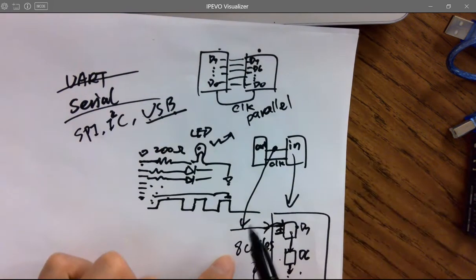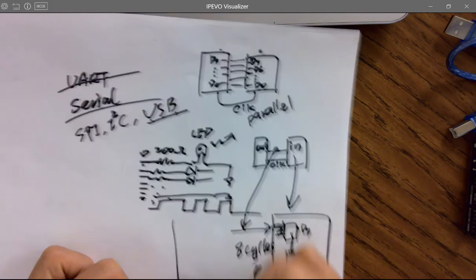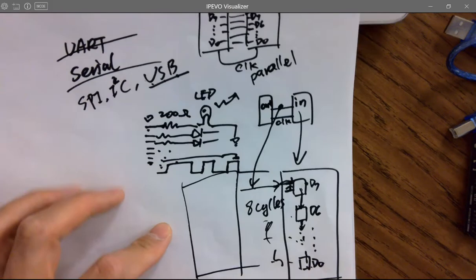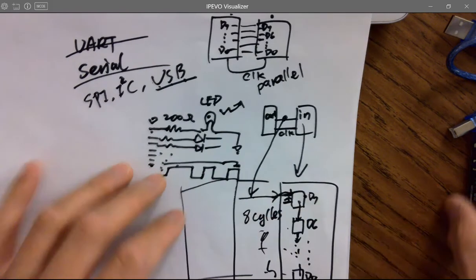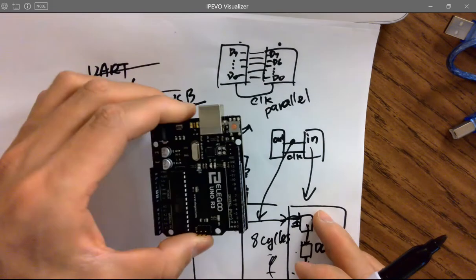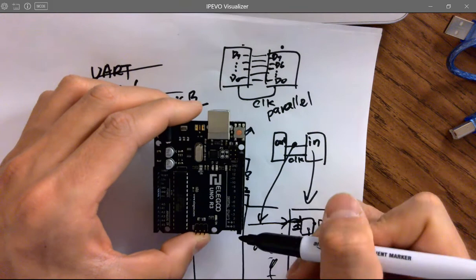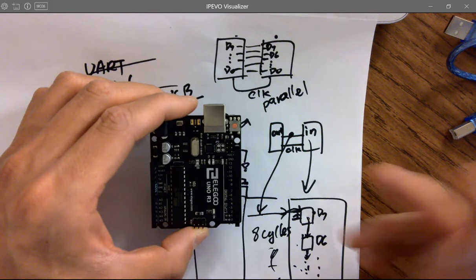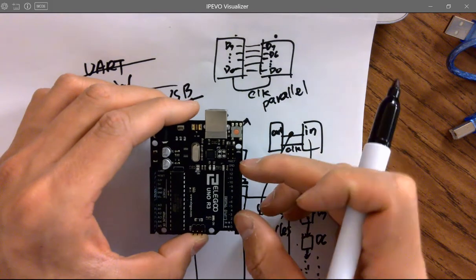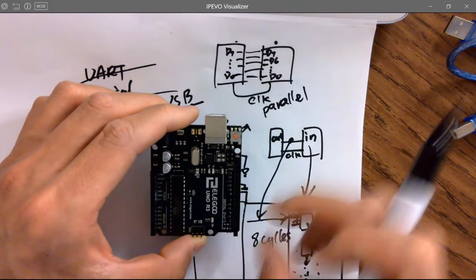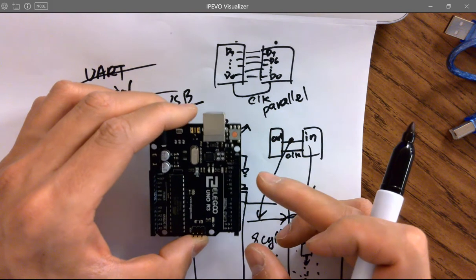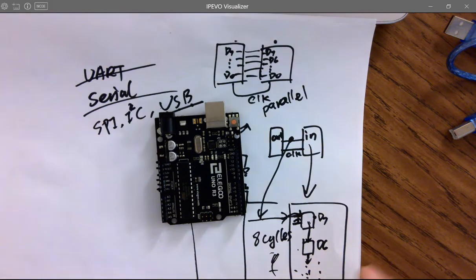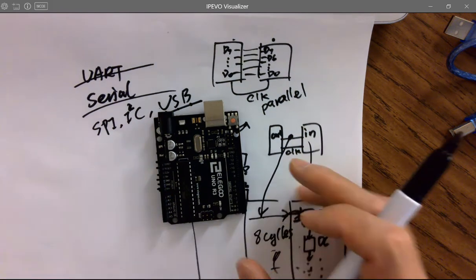For the serial, usually it's being used for chip-to-chip communication. The reason we prefer serial communication is because it's saving a lot of pin resource. If you look at this board, how many pins do you have? Not too many, from 13 to 1 to 0. Only 14 digital GPIOs. So if you use 8 of them to communicate with one device, you only have probably 5 left to communicate with another sensor. So sometimes you probably need like 20 sensors being connected to the microcontroller.